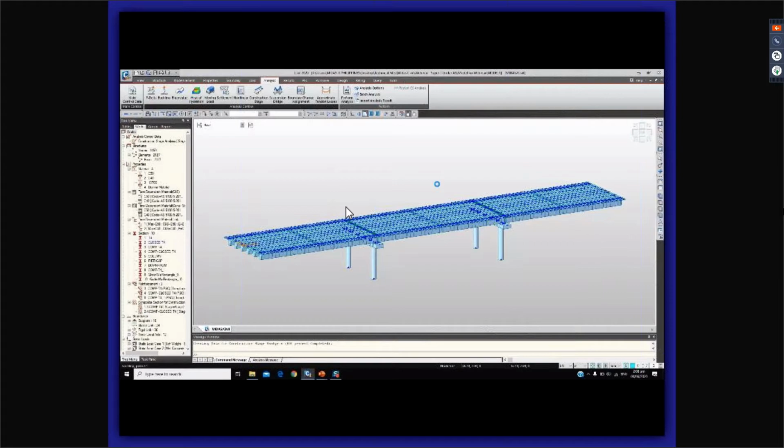So as you can see, analysis is conducted after 850 seconds. Now, when we go to the results tab, you can see the load combination function. You can click on combination, and then let's make use of the auto generation button.